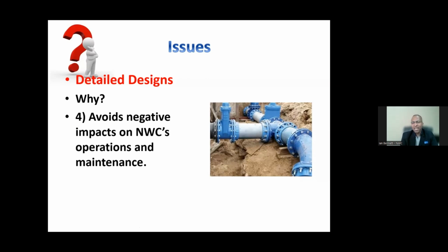If you're putting in, for instance, a large bend at a particular location, a pumping station, for instance, and you're putting in anchor blocks there, and it's a huge anchor block, the first day we have to do repair to any part of that infrastructure might dictate that we destroy that anchor block. So we may suggest to you that you use couplings which can take restraint joints, which are couplings which can take thrust, so that it's easy to disassemble and reassemble that particular fitting if repairs have to be done.